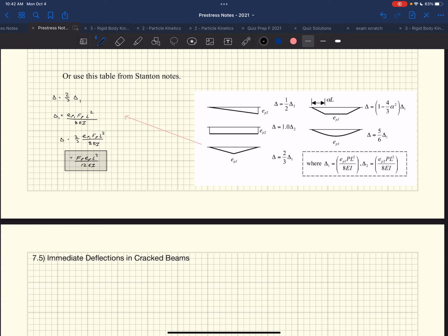Described and visualized with cables or chains suspended from 2 points that adjust their form for any load and tension. But funicular structures may also be compressed like arches. Although funicular tension structures adjust their form for pure tension under any load, funicular compression structures may be subject to bending and additional compressions. Okay, I like that one. And then catenary is another one. So they're close to each other, but they're not exactly the same.